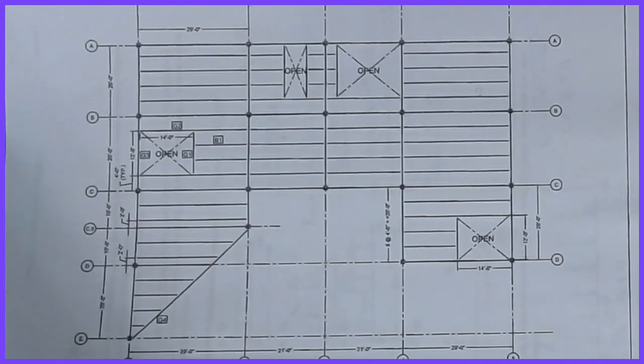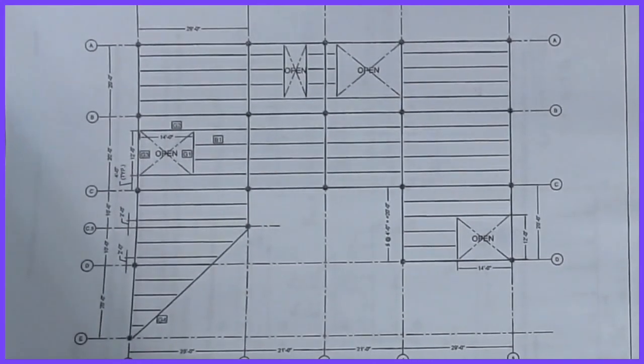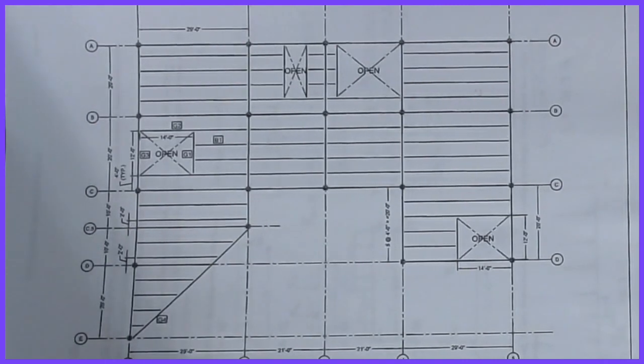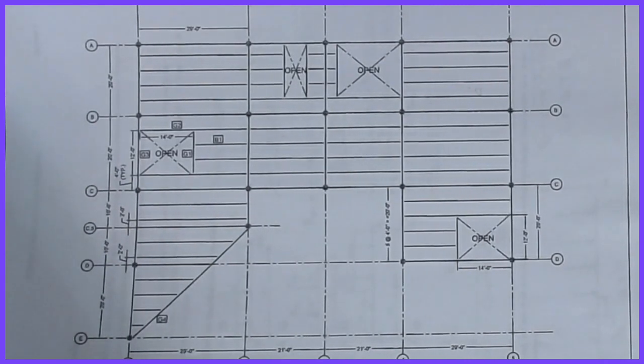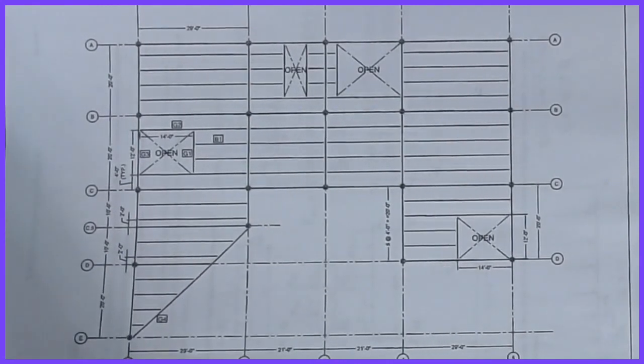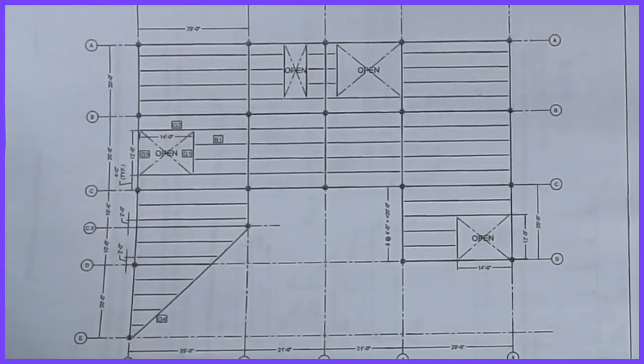What we need to look at is how we design the members or the structural framing to support those loads, and that's where these tributary areas will start to come in. Most of the time, it's a vertical load. We're dealing with plan view diagrams, which come from either the architectural drawings or from the structural framing if you haven't already made that. But the same approach also works for horizontally applied pressures such as wind or seismic effects, as long as you have the framing of the surface on which the load is acting.